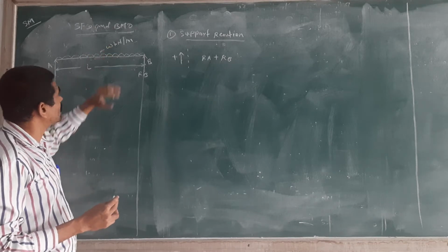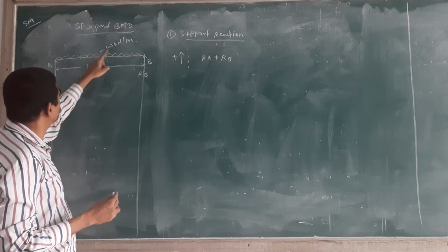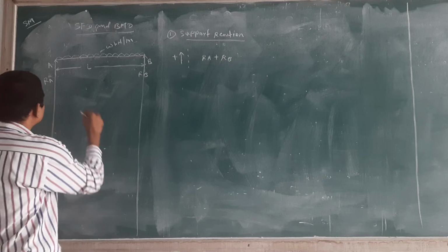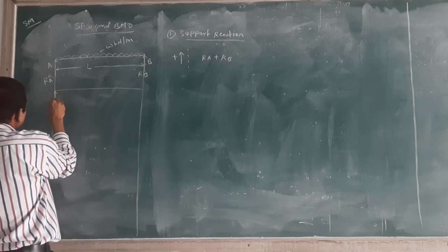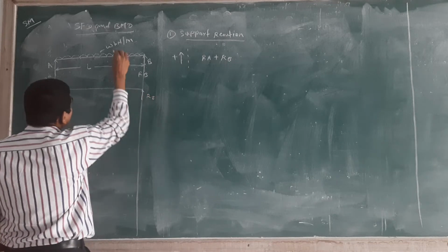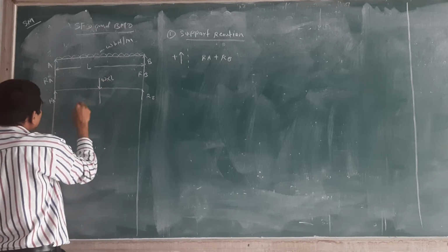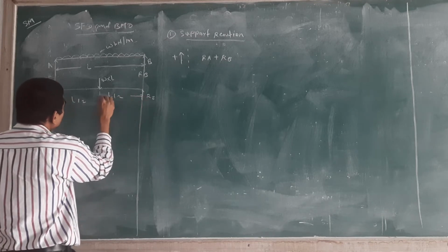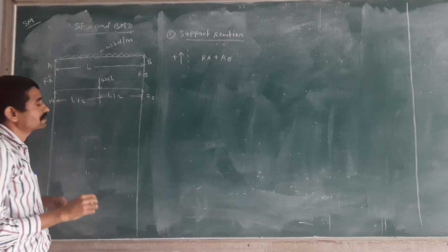How to convert that W into a point load? Force into distance. And where is it applied? At the CG. If you convert this figure, you will get RA here and RB here. This will act as a point load W into L at the CG of that figure, meaning L by 2 from the left end, at the center.